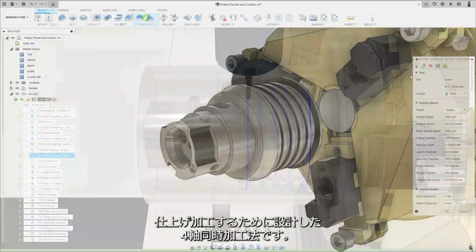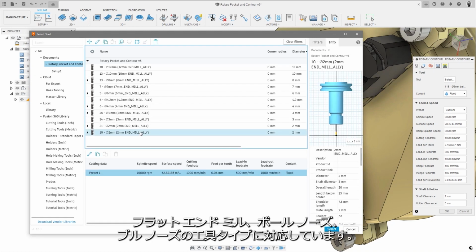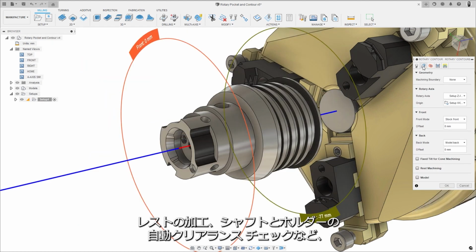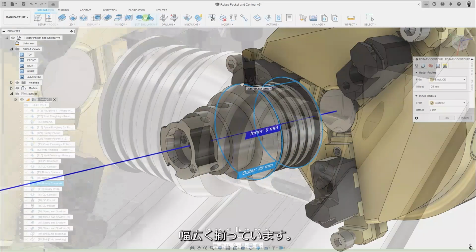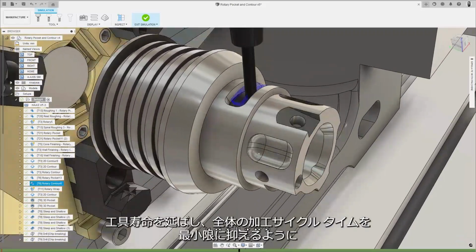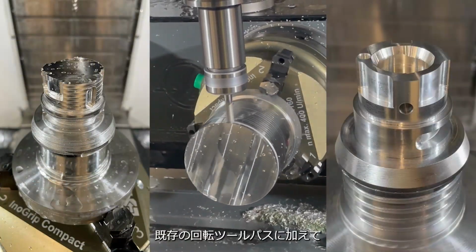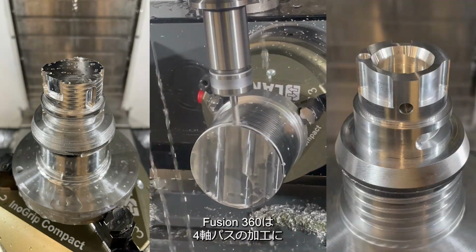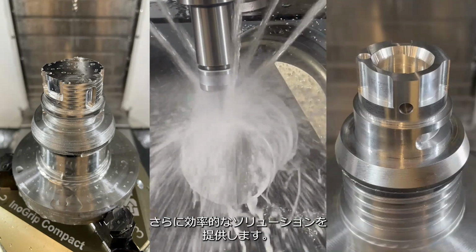Both rotary pocket and rotary contour strategies support flat end mills, ball nose and bull nose tool types, and have a range of options to control the toolpath, such as boundary limits, ordering options, rest machining, and automatic shaft and holder clearance checking. These options are designed to optimize cutting conditions to prolong tool life and help minimize overall machining cycle time. The combination of rotary pocket and rotary contour alongside the existing rotary toolpath means that Fusion 360 will provide a more efficient solution for the machining of 4-axis parts.